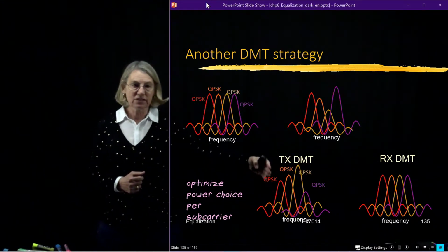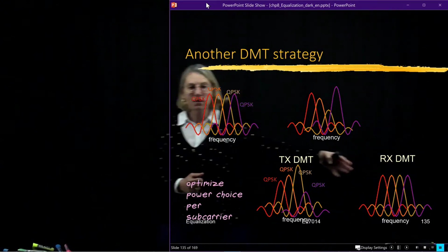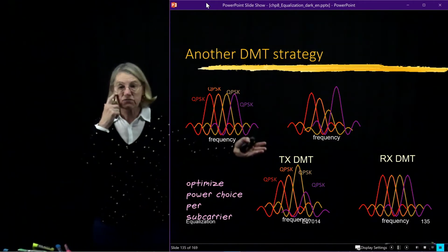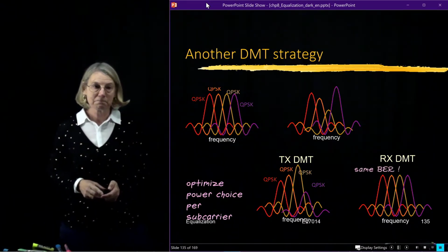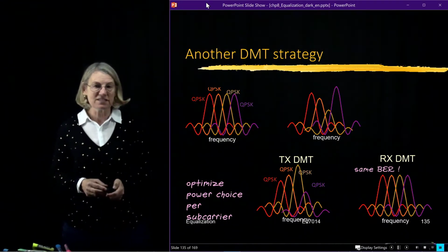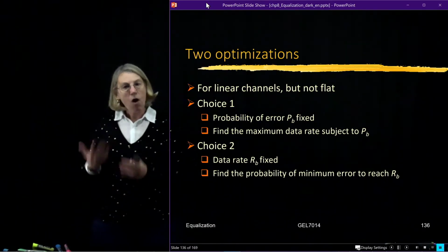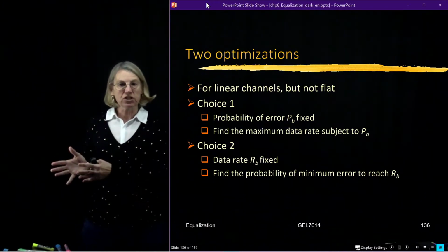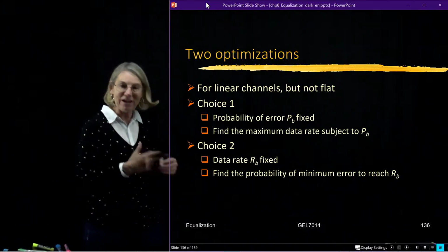For instance, we could have all of the received signal-to-noise ratios be equal, and therefore we could have QPSK, or the same modulation format for all of them, that would lead to the same BER. So the important thing is same BER would be achieved because of this choice. So we've seen how, very straightforwardly, we could change modulation, or we could change the power allocation.